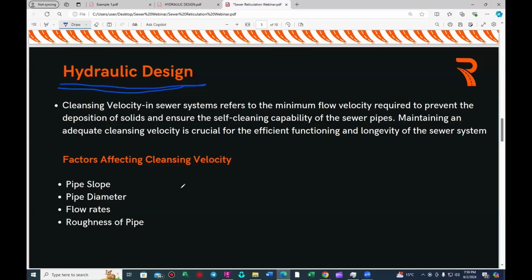It's socially disruptive, right? So if you under design your systems, what happens is that they will overflow. Then sewer is spilling all over the places, right? Risk of it contaminating your drinking water. We do not want that. Then if you over design, right, now that's another problem. If you over design, which means your sewers become unnecessarily large and they also become unnecessarily expensive.